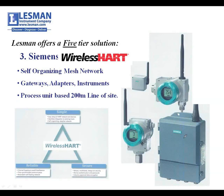Now, this stuff is designed for only about 200 meters, so this is close proximity, what we call a unit-based solution, okay? HART Wireless. A lot of your favorite manufacturers and vendors of instruments are all going to be coming out with equipment with antennas on it. You're going to see mag meters with antennas and vortex meters with antennas. This is moving forward at a pretty nice pace now.